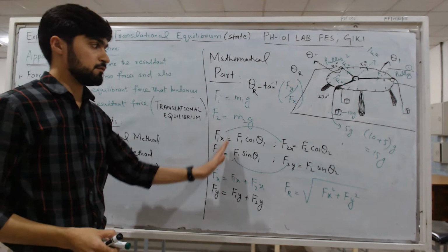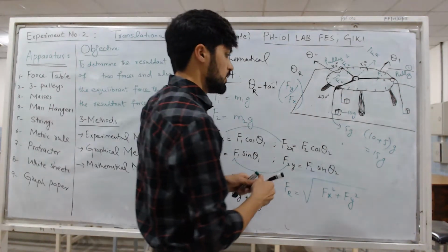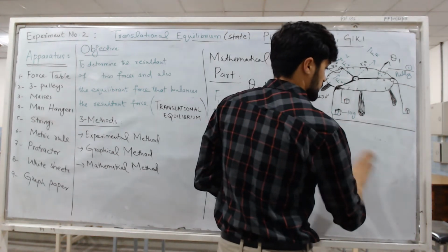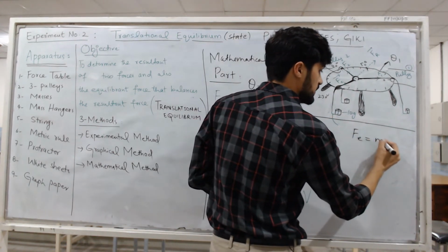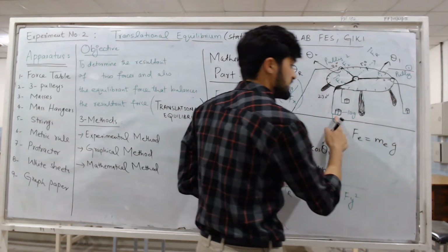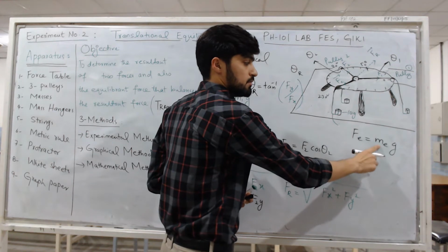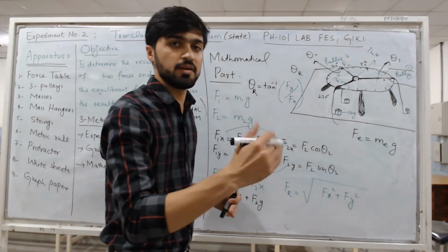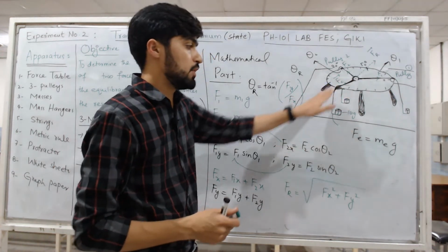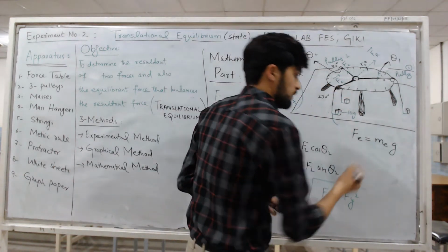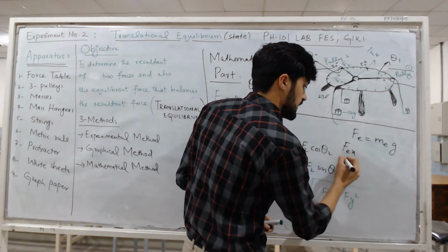You have to find the forces. You can also do it for the equilibrium force. This is the equilibrium force, so you can say Fe is equal to Me g. Me is the mass of the equilibrium, I'm using Me, equilibrium mass, just for the sake of simplicity, and Fe for the equilibrium force. So it must have two components, Fex and Fey.